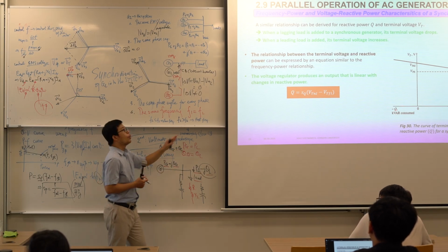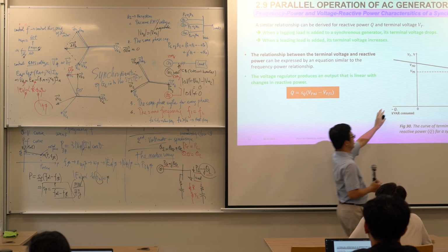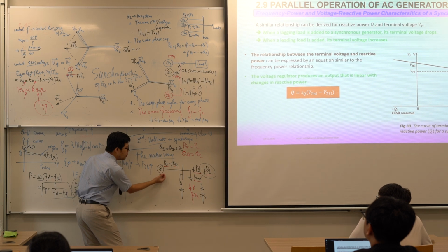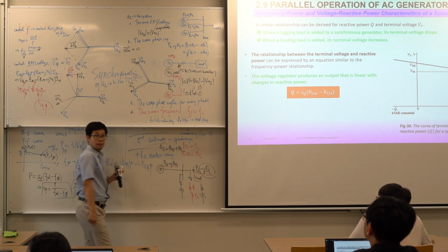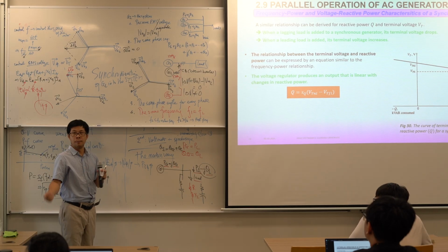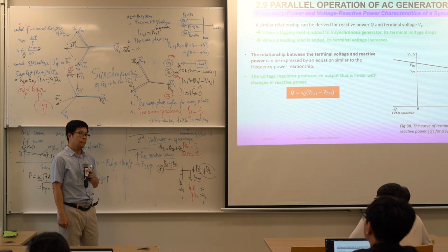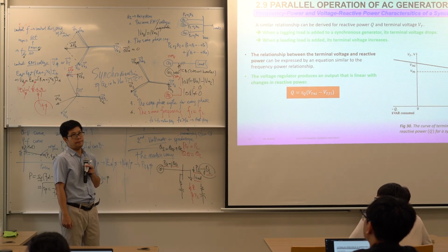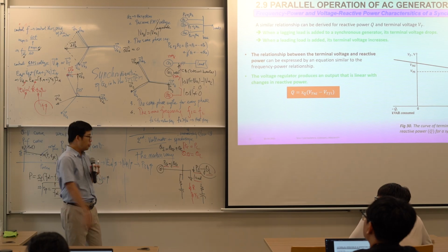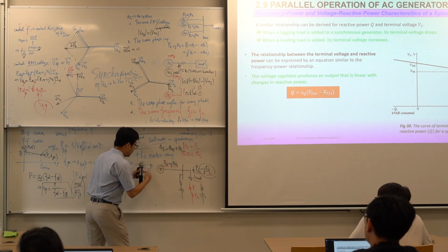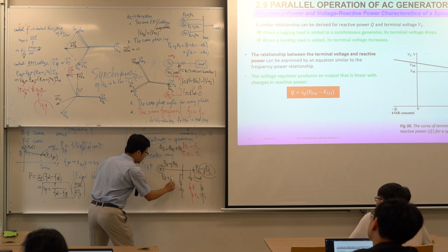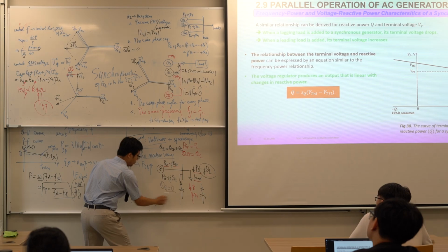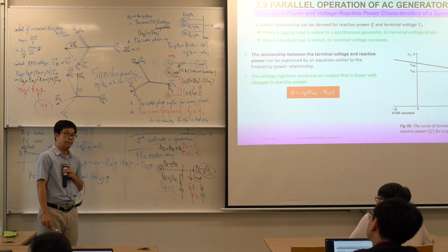But shouldn't do that. Why? Because if the synchronous generator consumes Q, that means more thermal, more temperature. Boom! The synchronous generator will be damaged. So you should make sure we generate PG and jQG, or for the ideal case, QG is 0. We hope.